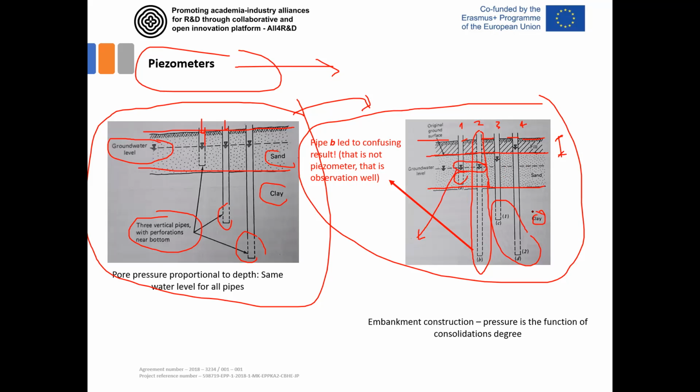That happened because clay material is very low permeable, with a low value of coefficient of permeability, and when you apply additional load, additional water pressure occurs in this layer. That's called excess pore pressure. It's the additional pore pressure generated in clay-like materials because the water in the voids actually takes all this surcharge load in the first phase of the construction.